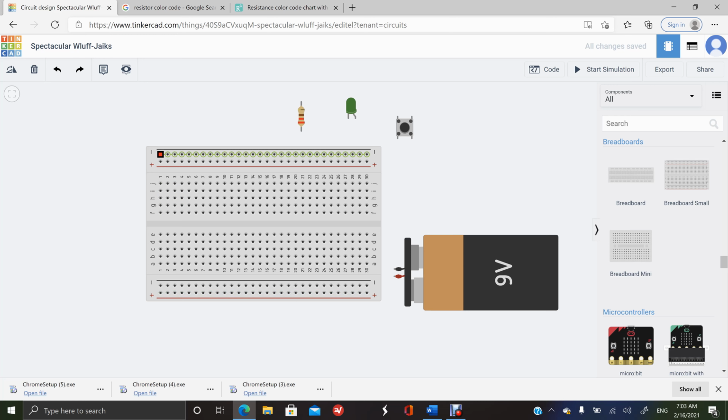So if you want to connect, for example, this and this, since they are negative for ground, all we have to do is click and then drag, and you can just make it look nice by double clicking, or just click one time, and then you can play with these nodes here to make it look nice. Okay, and you can change it by just selecting the wire that you create, and you just make it black. Normally ground is black.